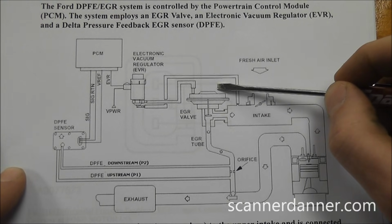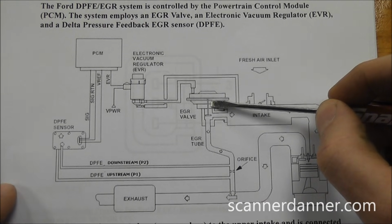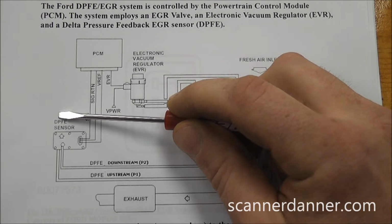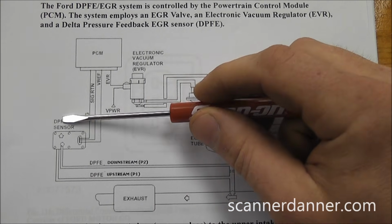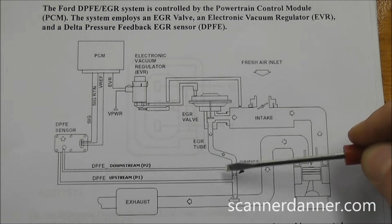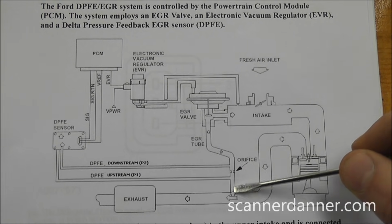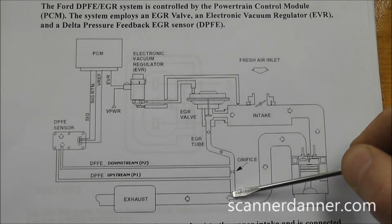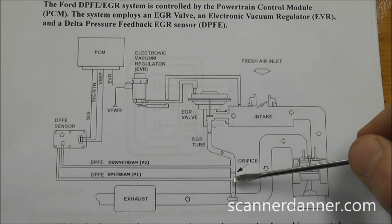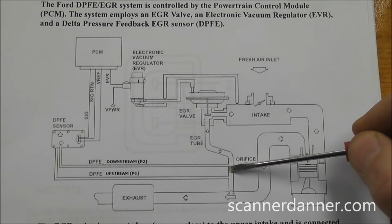So from there, the system is monitored for flow, and that's done by our DPFE sensor, which is over here. This DPFE, that's differential pressure feedback. It's called differential pressure because what it uses is two separate readings of pressure. One on the exhaust side of an orifice, that's our EGR tube. This will be that metal tube that runs up to the EGR valve from the exhaust. It's about maybe a 1/2 inch diameter, 3/4 inch diameter tube. So a pretty big tube, and it has an orifice or restriction in the middle of it.